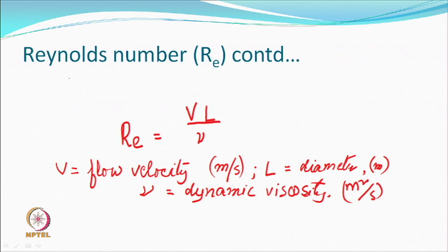So, if anything that you add to your ink changes any of these values, then the drop size and the stability of the drop change. For example, when the trigger has taken place, the liquid has gone out, something has become a drop or drops, then what happens to the meniscus? Does it keep dripping or does it go back?